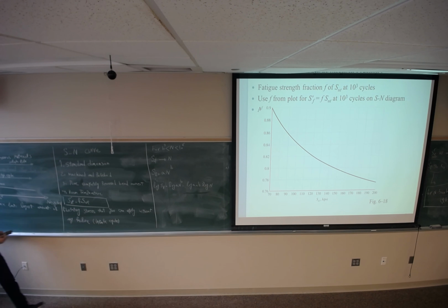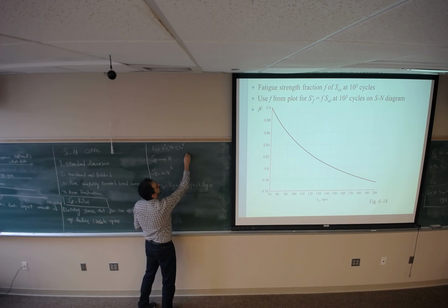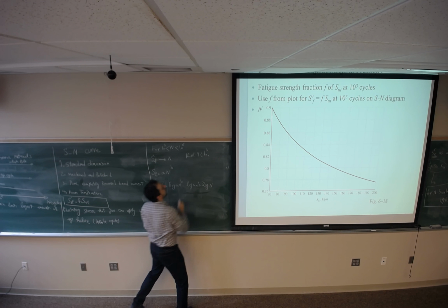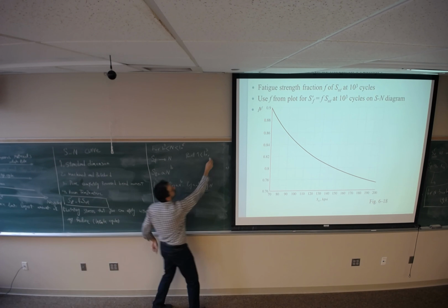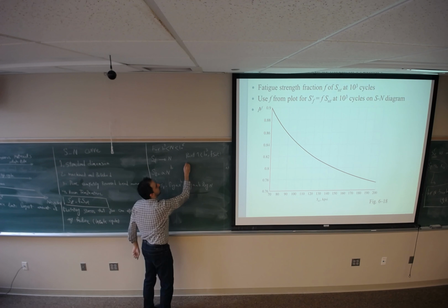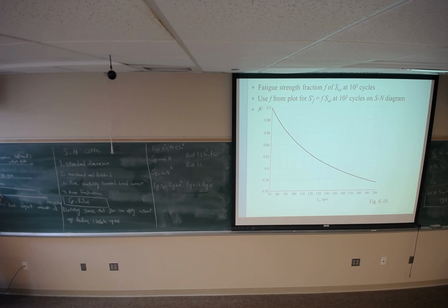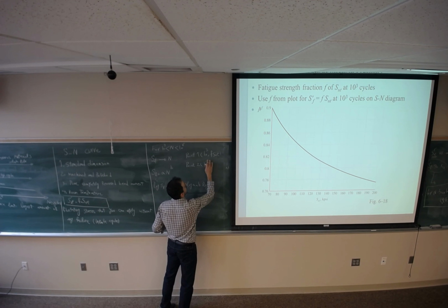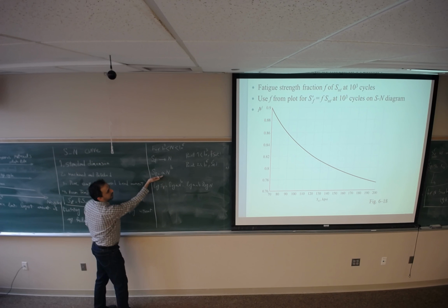So the fatigue strength should look like this as a function of number of cycles. Point 1 has n equals 1,000 cycles. This point has 1,000 cycles, and SF is going to be S prime L, which is F times S ultimate. Point 2 is the knee point with 1 million cycles and S prime E. So I have two pieces of information I can plug in here, to solve for A and B.